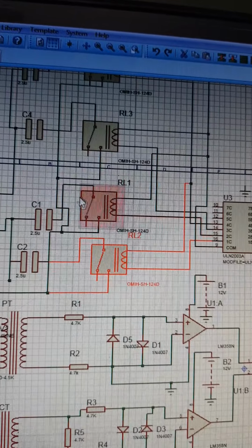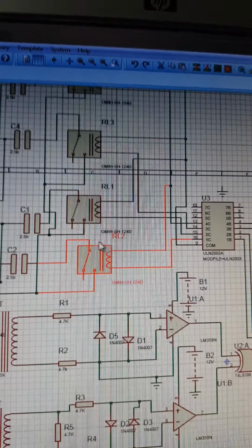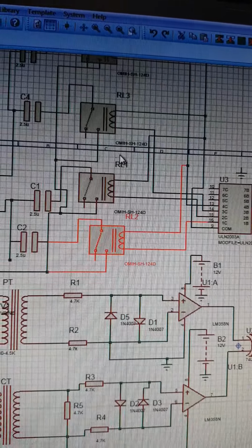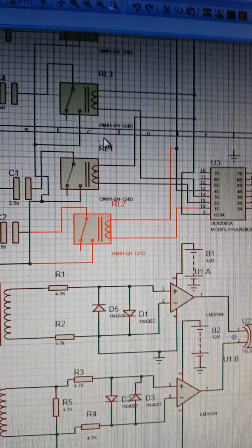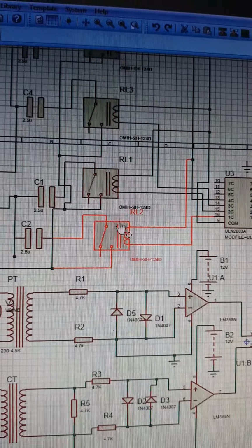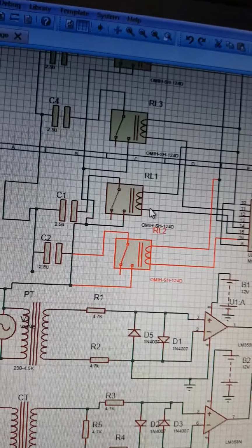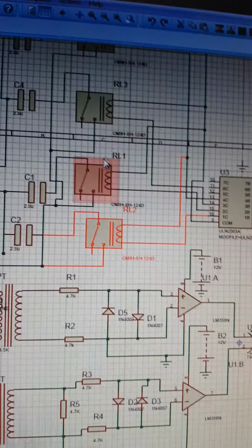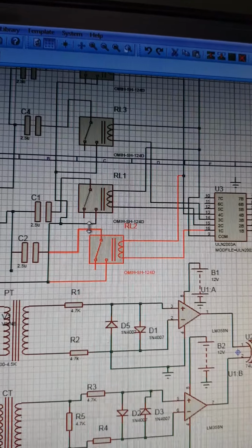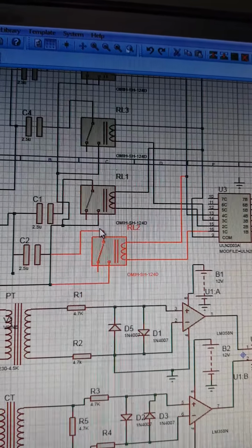But in most cases, or to be on the safer side, using SPICE model labeled components makes it easier for your simulations, because only the SPICE model labeled components are able to do the simulation. Not everything in Proteus is meant for simulation. Some of them are just there for schematic capture, right?